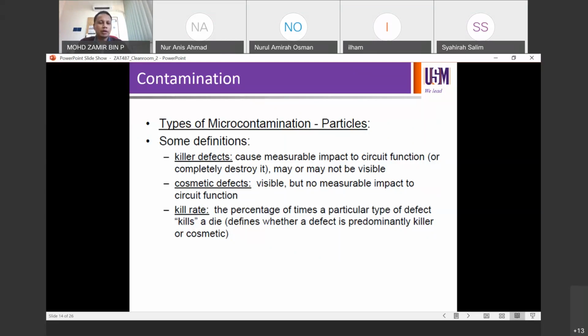Technically we call them qualification wafers, or qual wafers. If you work in a fab, you will be familiar with the keyword qual. Qual means the qualification process before you actually release the tool to run mass production. So you need to troubleshoot the equipment. If it's due to the process, then you have to troubleshoot the process, the recipe, or the parameters, fix them, and run the test wafers through the equipment and process again. Make sure there are no more circular defects on the test wafers. Once proven no more defects, you can release to production to run as usual.